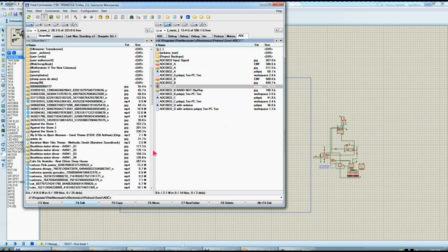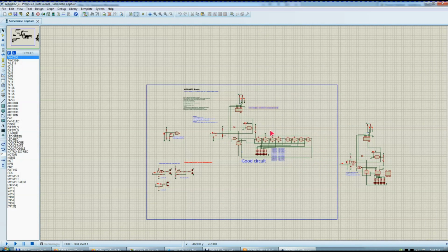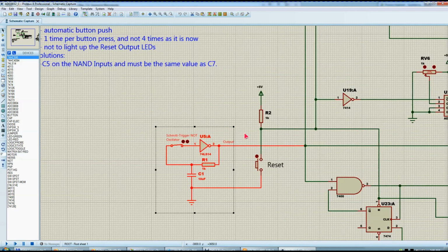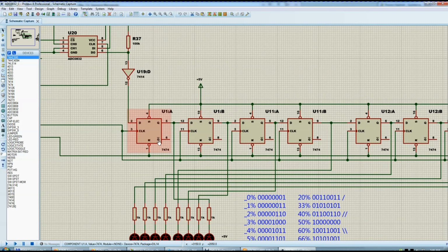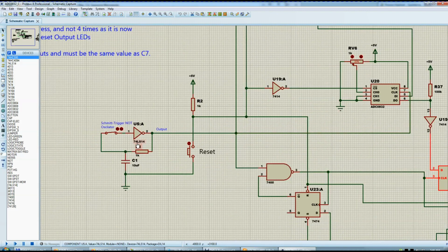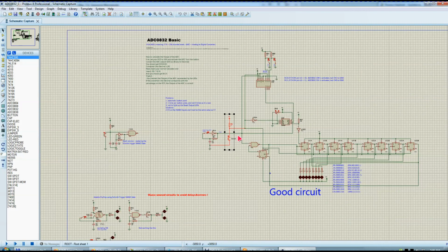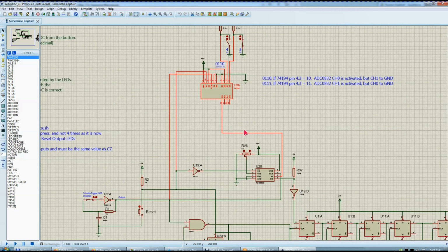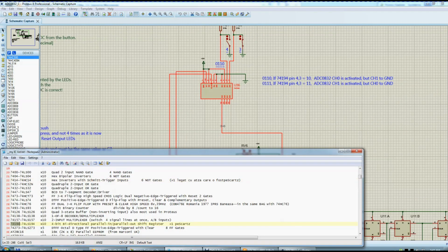So this was number B1, and now let's open the C1. And what I did here, I copied the same circuit that I have there, but I only changed, like I said, this clocking circuit with the NOT gate. I'm also using the chips that I have, all these flip-flops, 7474, I do have them. The 7414, I do have them. This is the button that is resetting this circuit. And I do have 74194, I think. Let me see. 194, yeah, I have 10 of them.